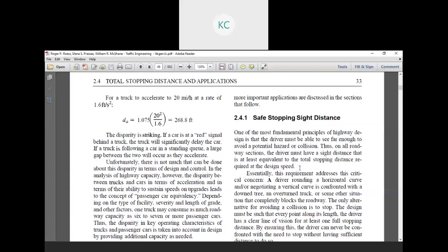When we talk about a national highway, the design speed for a passenger car is 100 kilometers per hour, and for a truck it is 80 kilometers per hour. This kind of speed regulation, speed signage, or the facility of speed studies is known as the design speed. Different classifications of roadways or highways have different design speeds.